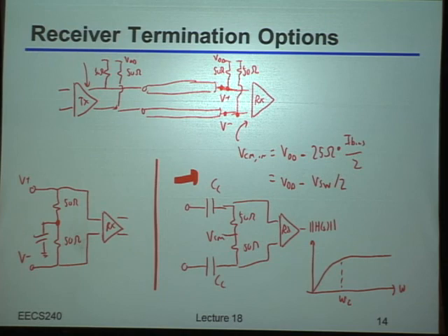So in the specific context we're talking about here, which is these high-speed chip-to-chip communication links, let's say as an example that this corner frequency was, I don't know, at a megahertz. Is that okay or not? And by the way, let's just make up some numbers. Let's say that your link is running at, I don't know, 5 gigabits per second. So is it okay to put it in megahertz or not? Okay, so you said probably and sounds fine. So it was indeed a trick question.